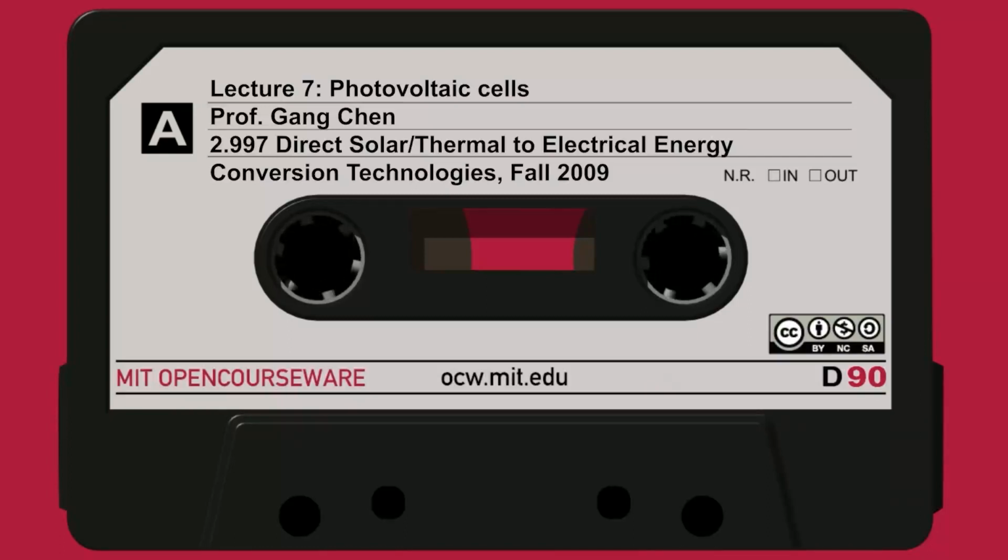So one idea is that if I make a Schottky barrier or potential barrier and scatter this part of the electrons, that's called an energy filter, or, if you have an interface, you also call it thermionic emission. Some people call it thermionic effect in thermoelectrics, or so-called solid-state thermionics. But essentially, it's cutting out the low-energy electrons, which sometimes carry negative heat because the electrons below the chemical potential carry it.